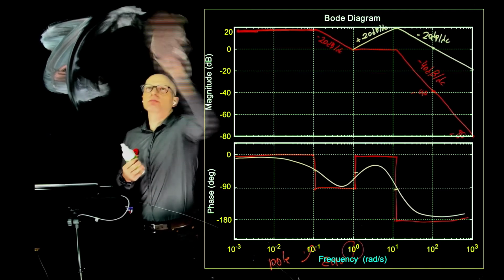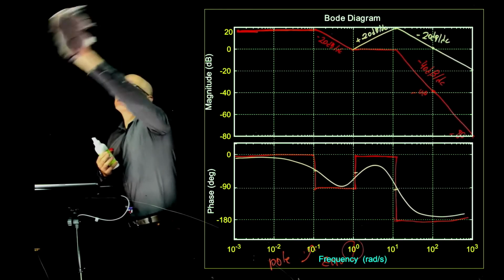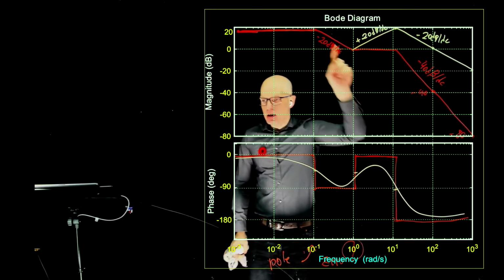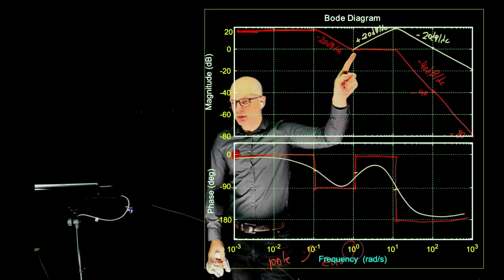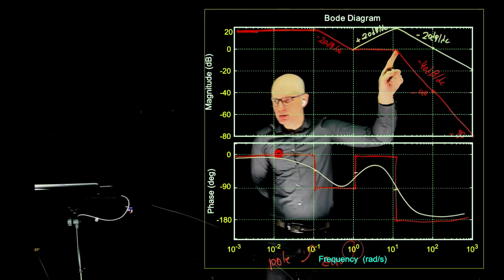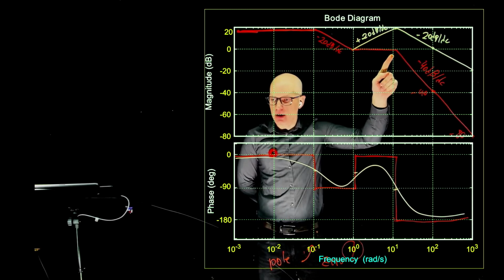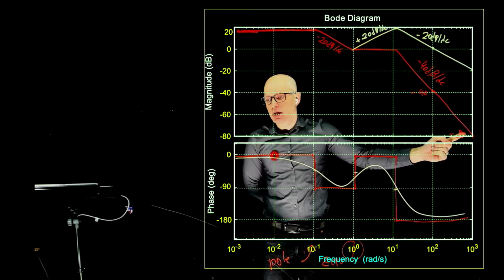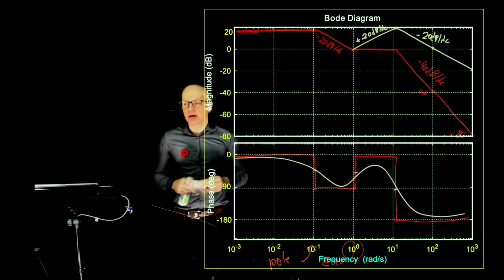So for the graph, we don't consider the -3 decibels. Oh yeah, if we consider the -3 decibels, we should, but for our purposes, it is enough to just do it this way. So if we consider the -3 decibels, here would be a -17, here would be a -3, here would be at -3 minus 3 minus 3, so -9, right? -3 for each pole, and then everything from there would start at -9, it would go -40, so -49, and -40, -89. It just shifts from the point where you reach that, everything shifts down.